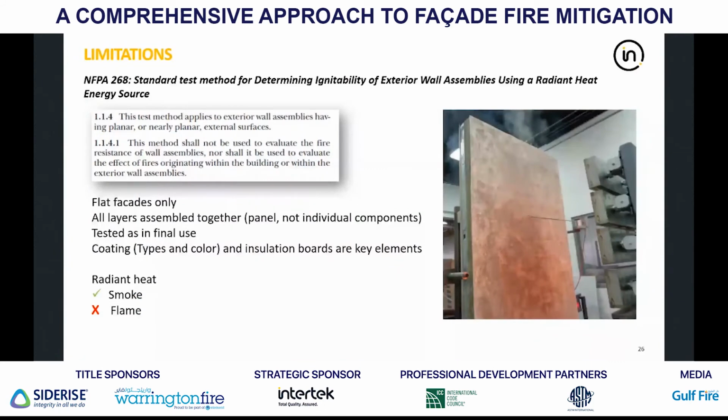So I mentioned at the beginning we would focus mostly on components, but this is the case where the standard is for the system you're going to install. This is a requirement for each system. So in here, this is a test that is applicable only to flat facades, and all layers are assembled together. You're not testing the individual components, you're testing a panel made of all the different layers.